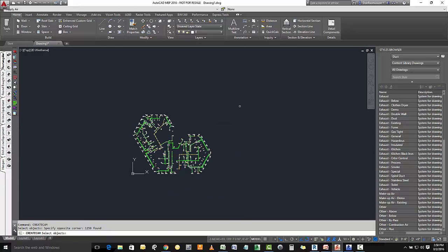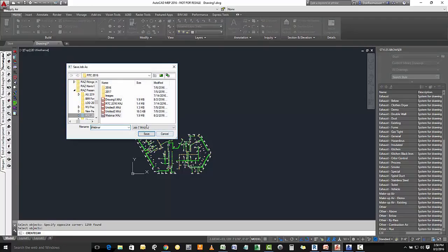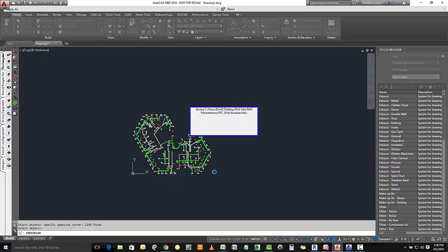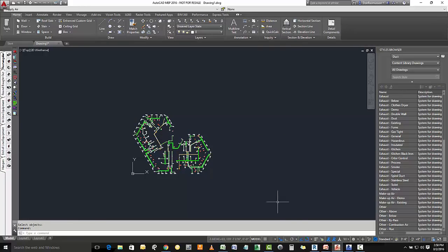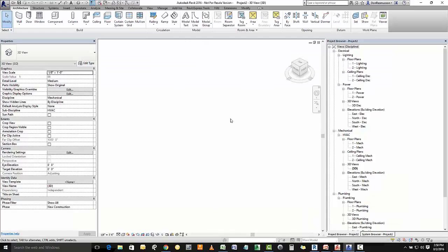Now it's important to note that this MAJ export is just going to take things that have been populated by a design line. All those graphical elements we did with the RIF export, none of those are going to come over. We're going to have to populate those either inside of Revit with fab pieces or with Revit content. But I'll have all these selected, I'll hit enter, and it'll create this MAJ file export for me. I'm going to overwrite this webinar one. Yes, I'd like to overwrite that. And then I'll go ahead and open up Revit again. Now here we are in Revit.